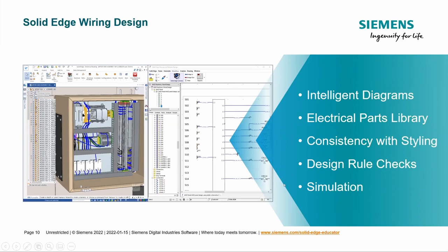Two other important things I want to call out at this time. The first is design rule checking. As we're creating this schematic, putting down devices and running wires, the design rule checker is running in the background to make sure that what we're putting down is electrically sound. For example, if we put down a component but didn't wire it up, we could easily miss that in a multiple sheet drawing. There's no limit to how many sheets you have in a design. If there are 100 pages or 300 pages, you can't possibly find where you may have left a component and didn't hook it up. So the design rule checker will help us with things like that.